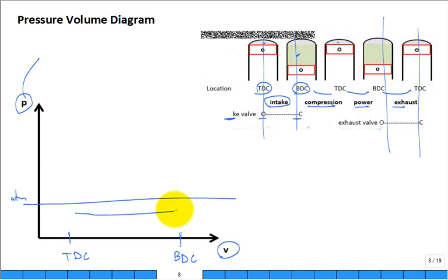Okay, so let's press forward now. We're understanding it's under a state of intake. Then it gets up here at the bottom dead center. It's going to stop. The pressure is probably going to come up. And as it starts to compress and go to the compression stroke, the pressure is going to go up, up, up, up, right? And then it's going to be near the top dead center. Maybe the spark kicks it right here. It starts the combustion a few degrees before top dead center. And then it's going to be a rapid rise in pressure. And maybe the combustion ends, but now you're beginning what stroke?